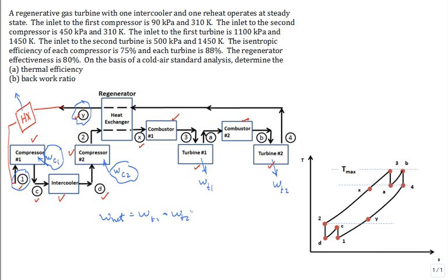What I'll do is calculate these as positive works for the compressor, and then I have to subtract them when I deal with the work net. I know the direction of the work transfer for the compressor. It's into the compressor. So I like working, like most engineers do, with positive quantities as often as possible.